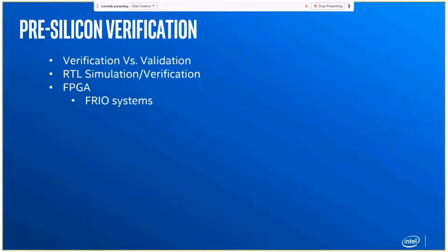So we build maybe 7-8 FPGA systems, and usually there'll be discussions as to, okay, we are going to put these two racks together so that you can mimic at least half the chip or something like that, and there are individual racks that will mimic just one block at a time. And the interfaces to other blocks are all understood, and we know what's supposed to happen. So you'll connect it, send traffic, see what happens, take it out.